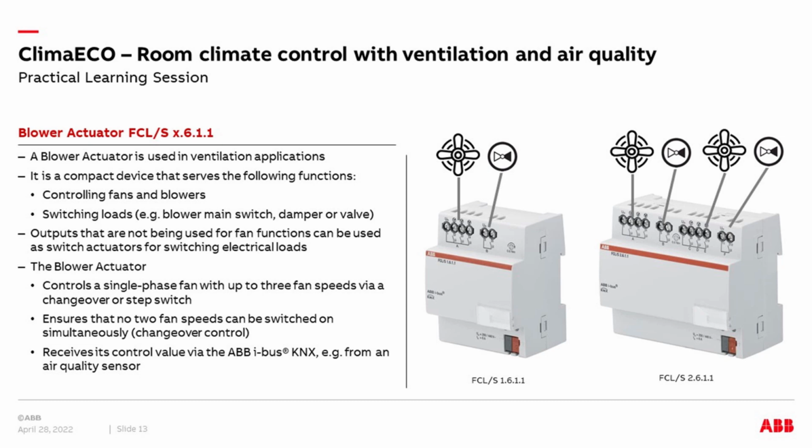And the way of control of the 3 relays is different from a normal switch actuator option, because we can have the so-called changeover or step switch control. What does it mean, changeover? Then I do not turn on the second relay in addition for controlling the second stage, but I turn off first of all the first relay from step 1, and then a bit later I close the second relay.